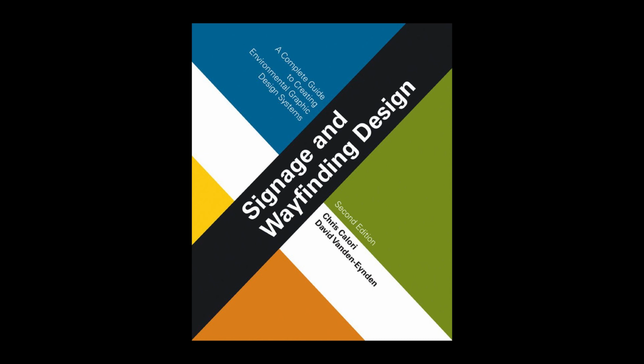As noted earlier about sign location plans, the design drawings shouldn't necessarily be prepared assuming they'll be reproduced in full color. In other words, it's wise not to rely on the use of color to communicate important information. For example, if a sign background color is blue, it should be noted as such in writing on the drawing. If this is not so noted and the drawing is reproduced in black and white, there is no way to know that the sign background is blue. These annotations, which indicate colors, materials, finishes, and so on, are referred to as callouts.